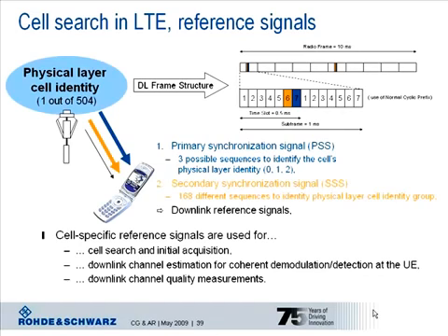The difference translates to a so-called channel quality indicator, a CQI value, which is reported back to the network. The CQI value stands for a specific modulation scheme, QPSK, 16 QAM or 64 QAM, and which channel coding should be applied to the data. In that matter, the cell-specific downlink reference signal could be seen as a lighthouse, where the power level refers to the height of that lighthouse.